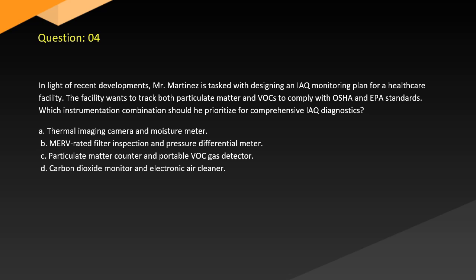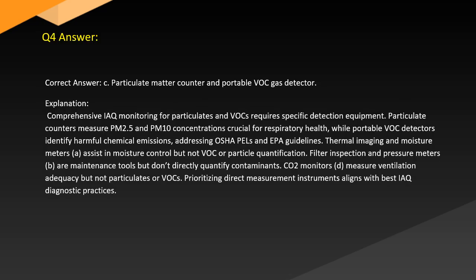A. Thermal imaging camera and moisture meter. B. MERV-rated filter inspection and pressure differential meter. C. Particulate matter counter and portable VOC gas detector. D. Carbon dioxide monitor and electronic air cleaner. Answer. Correct answer: C. Particulate matter counter and portable VOC gas detector.